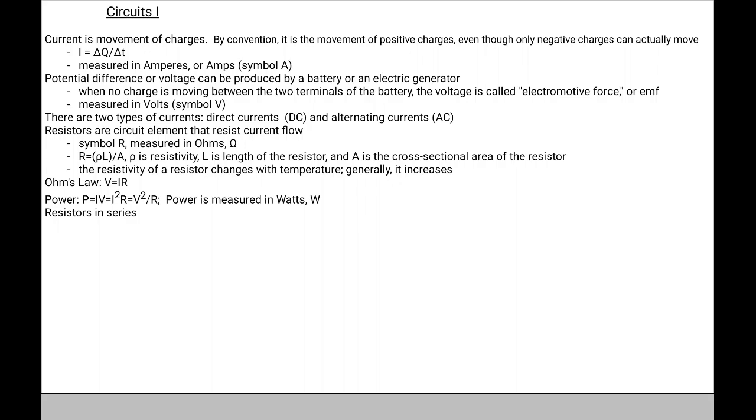Now, we can connect several resistors in a circuit, and let's say that we have 3 resistors in series. So I have R1, R2, R3. And there's a battery here. So here would be my EMF. Now, we know that the positive terminal is the longer one, the negative terminal is the shorter one, so we will have a current flowing through this circuit in this direction.